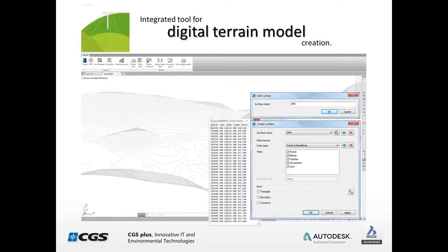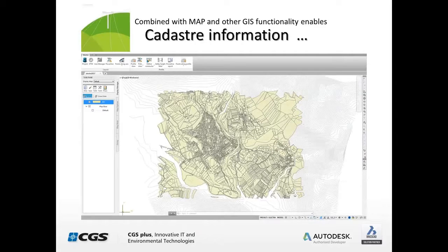Electra comes with a digital terrain modeling because of its support for the basically Bricscad and plain AutoCAD and Map softwares where there's no digital terrain modeling tool. So CGS DTM is already part of Electra, so that user can create any terrain from any ASCII file containing north, easting, and Z values. Okay. Here is one part that was mentioned before.